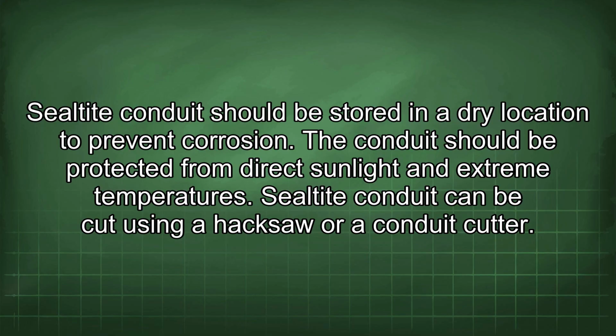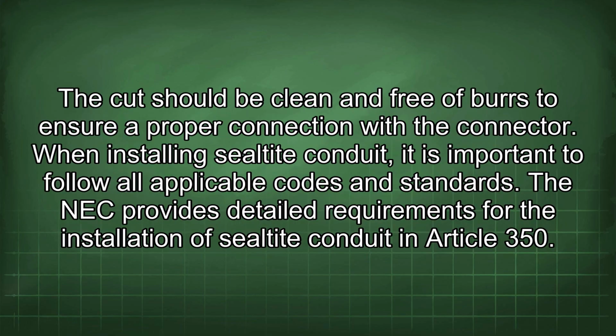Sealtite conduit can be cut using a hacksaw or a conduit cutter. The cut should be clean and free of burrs to ensure a proper connection with the connector. When installing Sealtite conduit, it is important to follow all applicable codes and standards. The NEC provides detailed requirements for the installation of Sealtite conduit in Article 350.